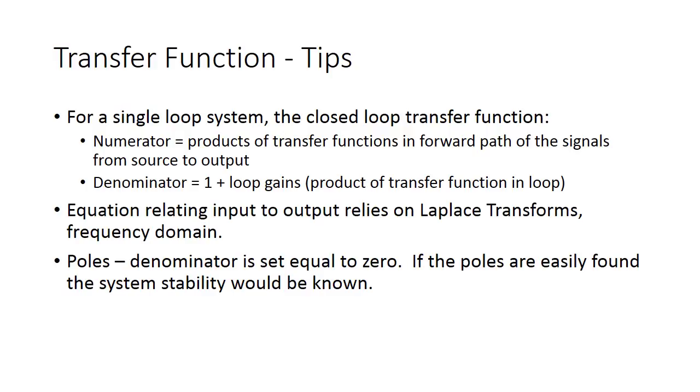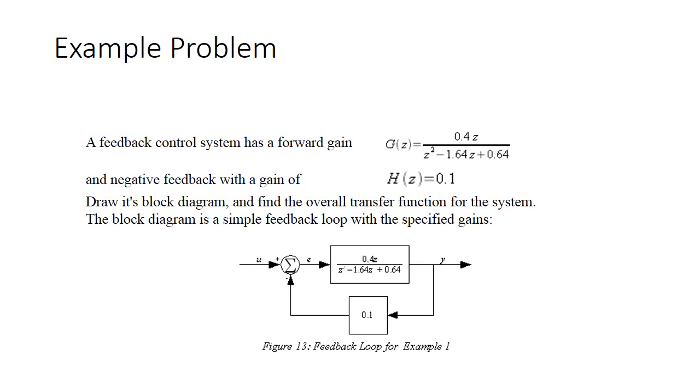Feedback. A closed-loop transfer function in control theory is a mathematical expression describing the net result of the effects of a closed loop on the input signal to the circuits enclosed. The transfer function for the above diagram is Y(s) divided by X(s) equals G(s) over 1 plus G(s)H(s).